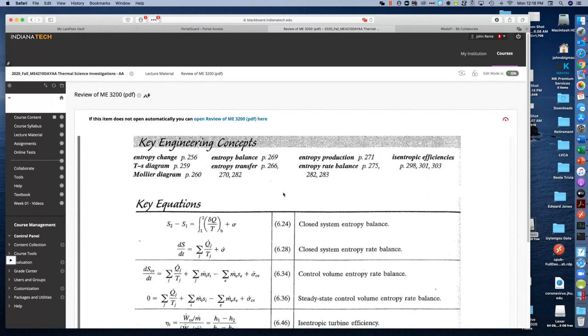One of the things that I always bring up is that there is no such thing in thermodynamics as the conservation of entropy. The equations that we have for entropy are only a balance of entropy, as opposed to a conservation of entropy. Entropy can be destroyed, and we will see that entropy can be produced. We will be looking at that as we go through our various processes.